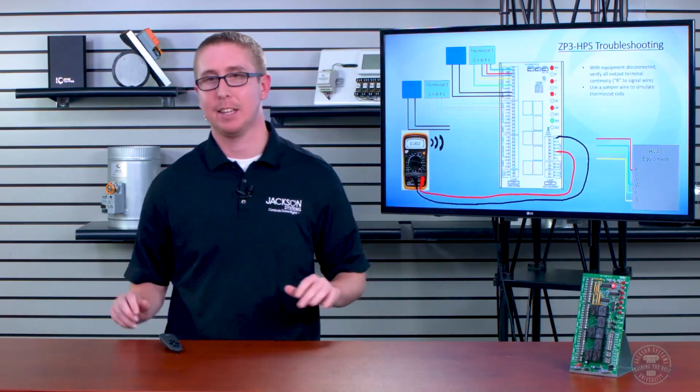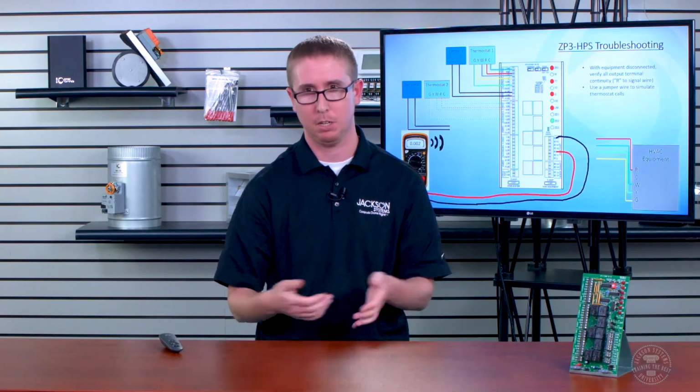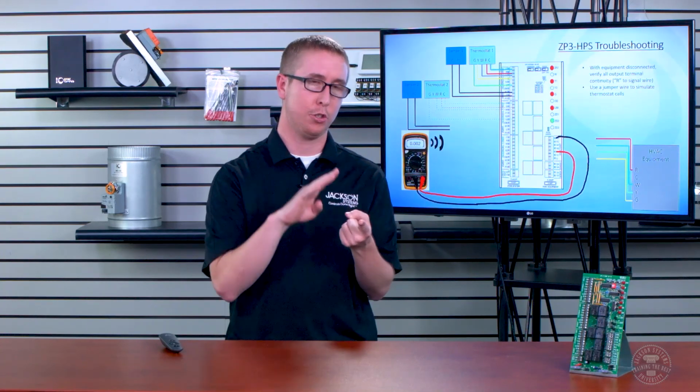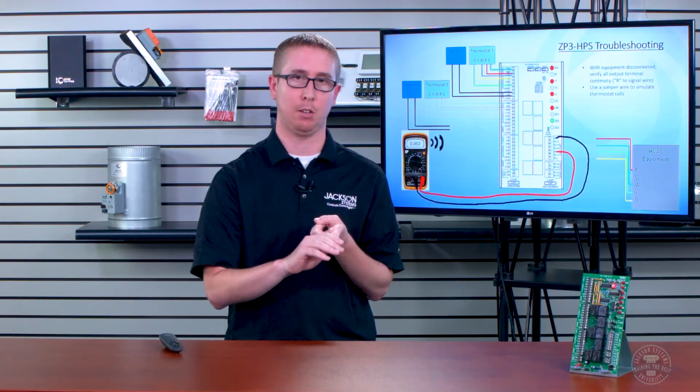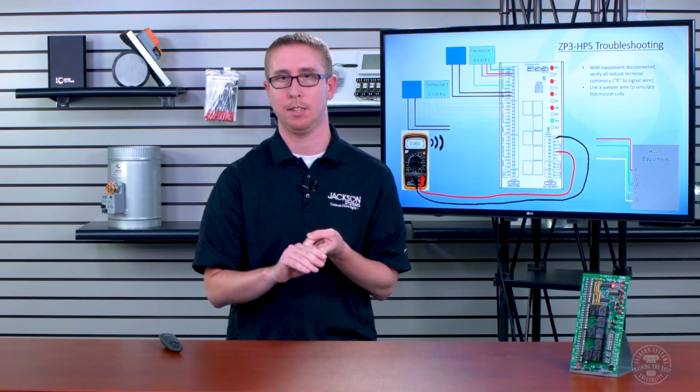just means that if a zone panel receives contradicting calls, and any given zone is calling for cooling at the same time as another one's calling for heating, what does the panel do about that? So from IO, all 2 and 3 zone panels, whether they're ESP or standard panels, are first call priority. That means if the heating call came first, heating wins. If the cooling call came first, cooling wins.